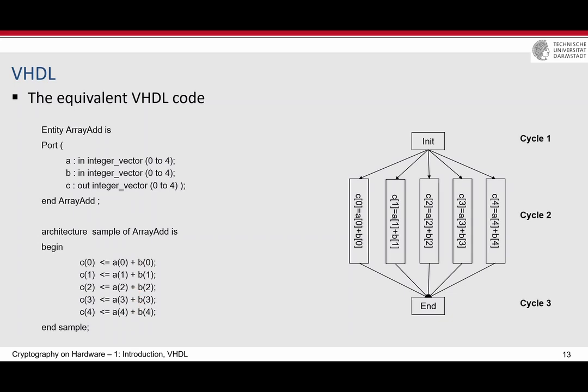to build these additions. I guess you already learned the adder, how we can implement the adder in hardware. If you don't remember, I can give you some names like Carry-Lookahead adder or Kogge-Stone adder, if the names are familiar to you. But now in hardware, what you do is you just write the addition, and then the synthesizer will use some libraries that it has to build this adder. Of course it will try to build the best adder, depending on how good the synthesizer is. And then everything will be just a combinational circuit, and these additions are performed exactly at the same time, at once.